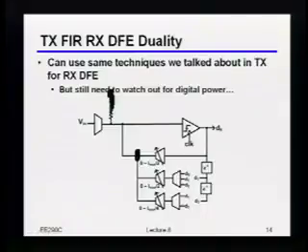So don't get me wrong, you can do all the peaking, you can do all the high bandwidth tricks that you'd like to do. I will mention, however, that the inductor will probably be 5 to 10x larger than the rest of the circuit. But yes, you can absolutely play those tricks. I'm not opposed to it. Unless you're really pushing on the speed, that tends to be just expensive from an area standpoint. Other questions on this?